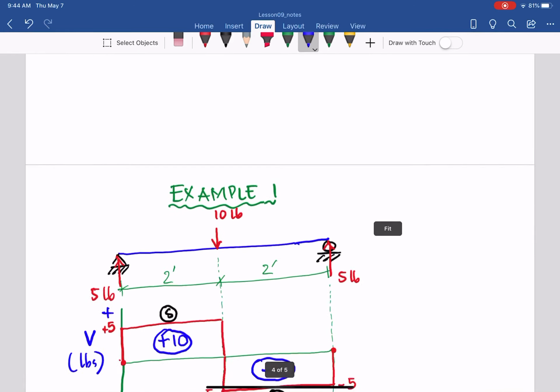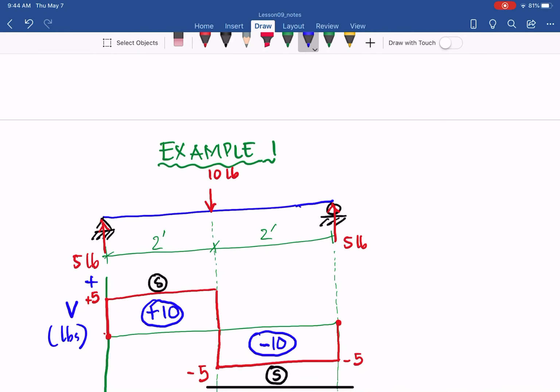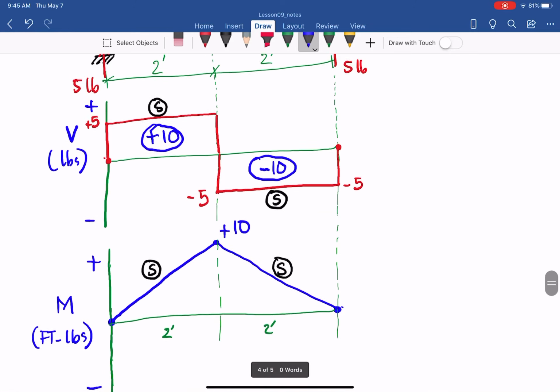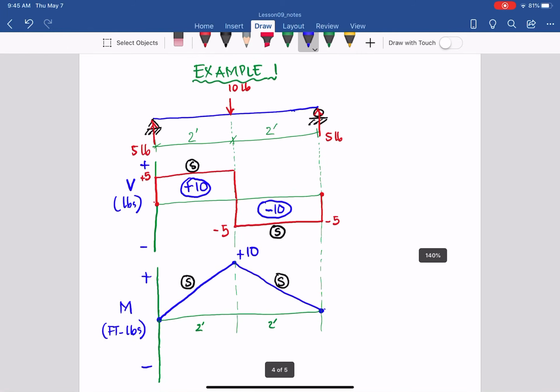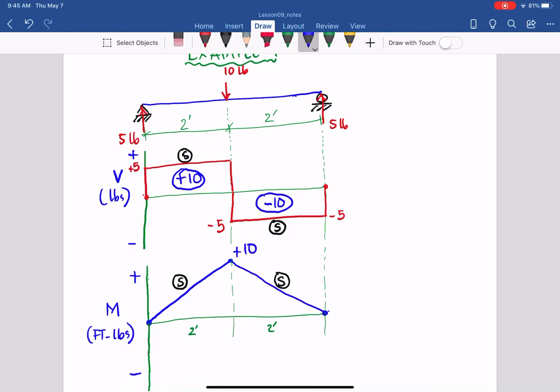It makes sense, because with that 10 pound applied, it creates for the whole beam from left to right tension in the bottom and compression on top, and with that the moment is positive. So that's why in a simple support beam you always have a positive moment. And that's shown in the moment diagram. That's the first example; we have 3 more examples to go.